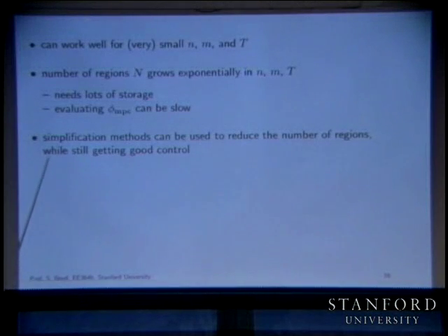Now you can do things to simplify these and get quite good control. And there's another advantage to an explicit form. An explicit form is actually quite traditional in control. That would be called gain scheduling. The person who's traditionally trained to make sure that control code is correct before it is downloaded into something dangerous or expensive will be very familiar with a switch, a big C statement with a bunch of cases, and in each case it dials in a gain. That's completely standard.